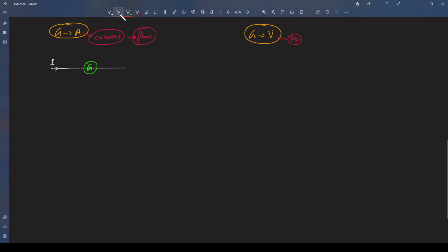So what I should do is, I'll actually connect it to another resistance, right? Basically, this is nothing but a bypass. Let's say, we actually use the word shunt for this. Shunt is a resistance in parallel. So I connect a shunt, or a resistance in parallel, to the G, right? What about this S? This S has to be a very small value.